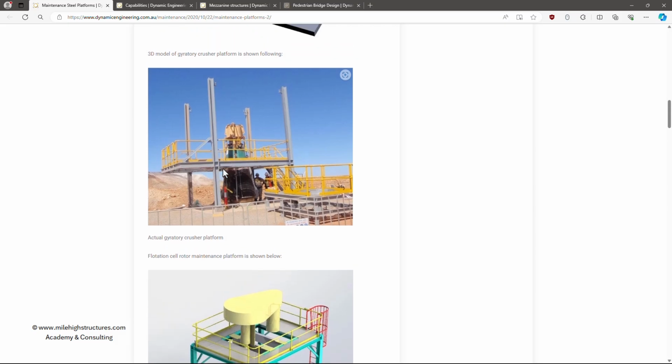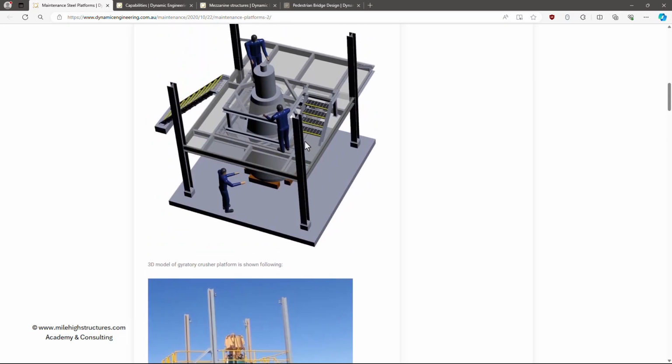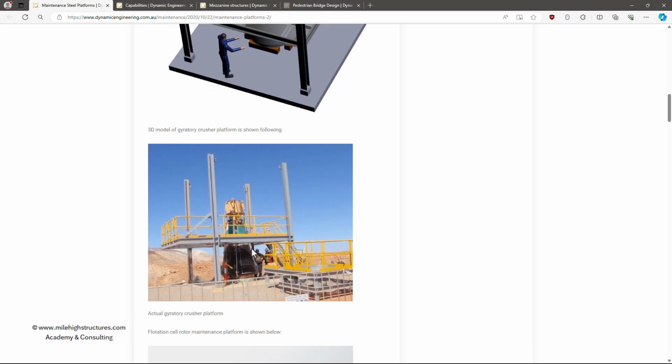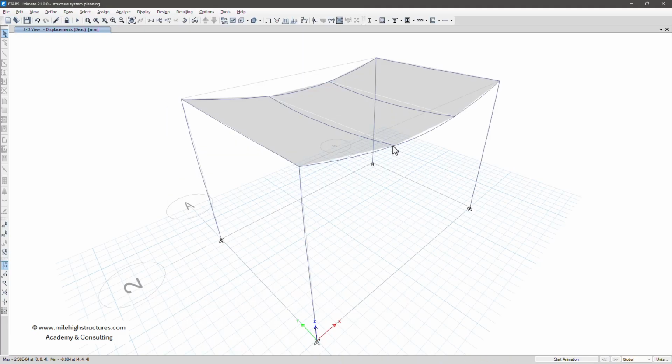It is always recommended that when we're talking about the plan, this is the moment frame, this is the shear frame. So it is better that we could have rotated this column here; this could have been the moment frame, this could have been the shear frame, and the steel utilization of this building would have been much lesser as compared to what it is made here. So here we can see that it has a deflection of approximately minus 0.8 mm.